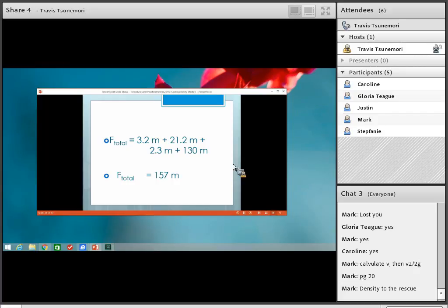And then if we want the static pressure, it's going to be the total pressure minus the velocity head. So it would be PT, which is 157, and we've got to check units here, but essentially the 157 minus the v squared over 2g, which is your velocity head. Remember, total head is equal to the static head plus the velocity head. Okay, so that's essentially the answer for our problem.